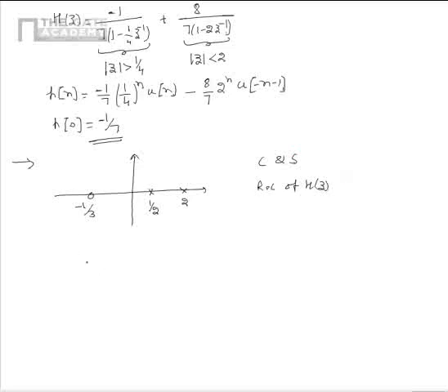From the given poles, we see that the ROC should be bounded by poles and it shouldn't contain any poles. So the possible ROCs are |z| < 1/2, 1/2 < |z| < 2, and |z| > 2. For the first ROC, that is |z| < 1/2, the system would be anti-causal, hence non-causal, and unstable as it doesn't include the unit circle.